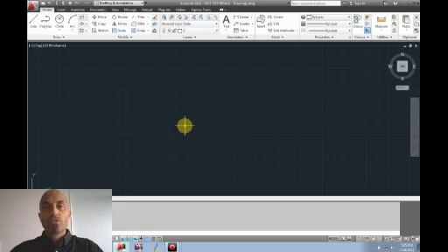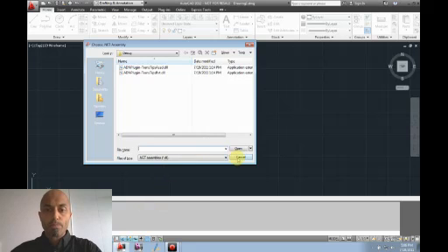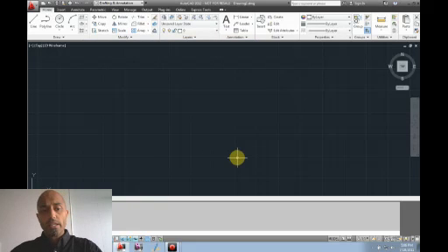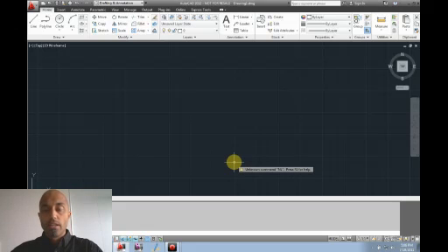So right now, yes, you have command complete inside AutoCAD, which is great, but for certain commands that I use a lot, it's nice to have little shortcuts in order to launch them quickly. One command that I'm using all the time, for example, is netload. Right now, I can type in netload, and sure enough, it comes up. But what I'd really like is a little shortcut, so when I type NL, it comes up instead. At the moment, if you type NL, nothing will come up.